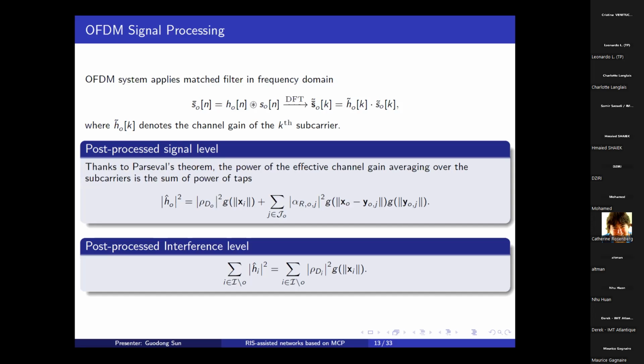The channel power in the frequency domain is the sum of the power in the time domain. This is Parseval's theorem in the Fourier transform. So we understand the superposed channel is dispersive, with some delays. If you consider this dispersiveness, it would be a problem in the physical layer. But when we use this modulation technique, we can overcome that up to a certain degree.